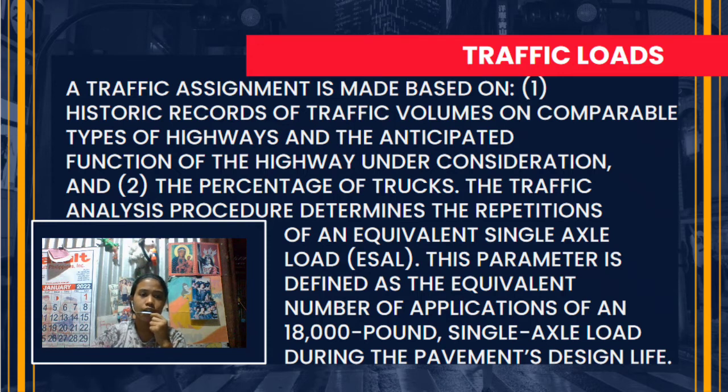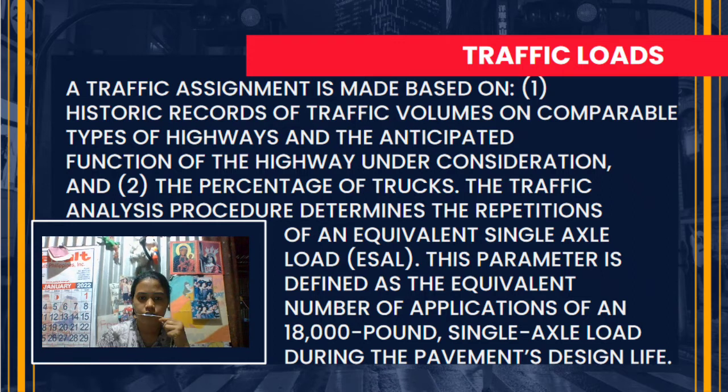So, the design year traffic volumes are estimated at 25,000 and 20,000 vehicles per day, respectively, on the major and minor roads. The posted speed limits are 45 miles per hour, 72 kilometers per hour, on the major road and 35 miles per hour, 56 kilometers per hour, on the minor. There are sidewalk facilities along all approaches, and the intersection serves a daily volume of 2,400 non-motorized road users. Next is the percentage of trucks.